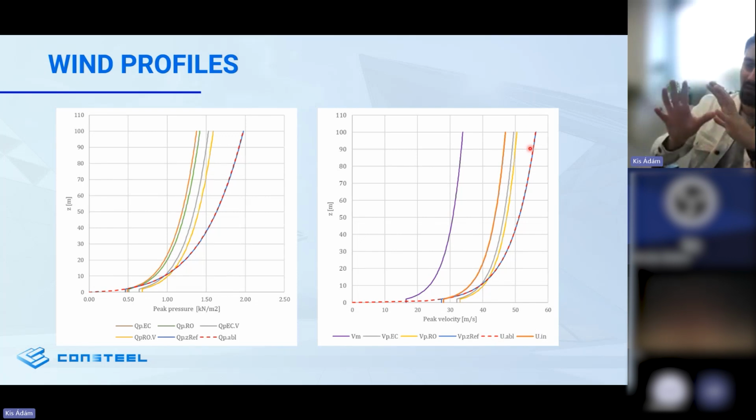What I would like to highlight here is that neither the basic OpenFOAM profile is suitable, nor does the Eurocode wind calculation method exactly produce those pressure values that we are waiting for.